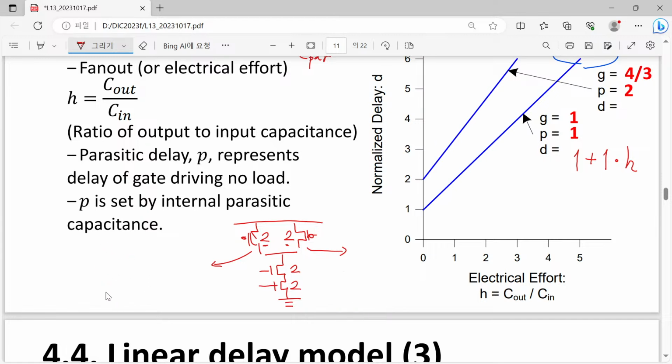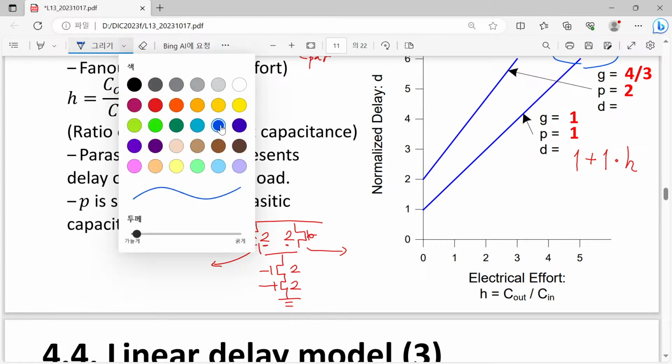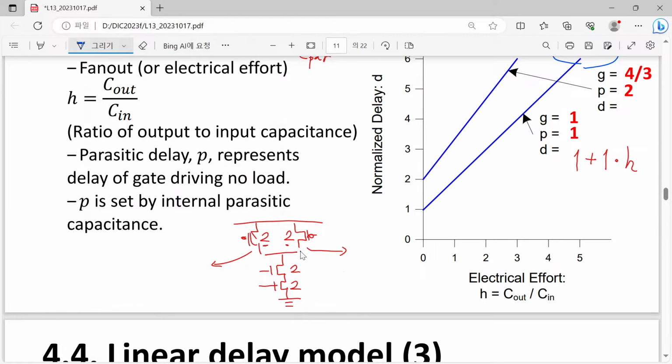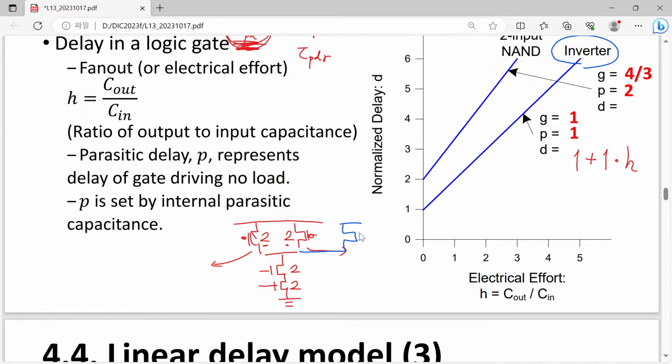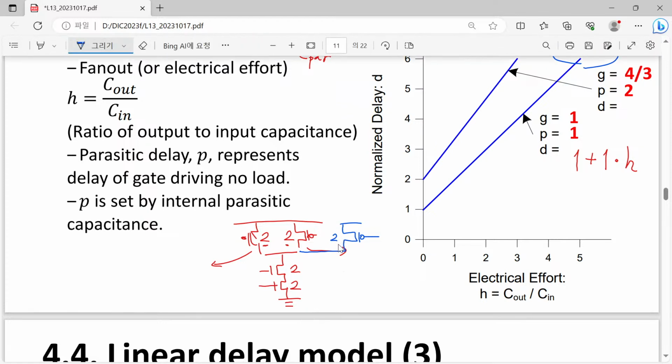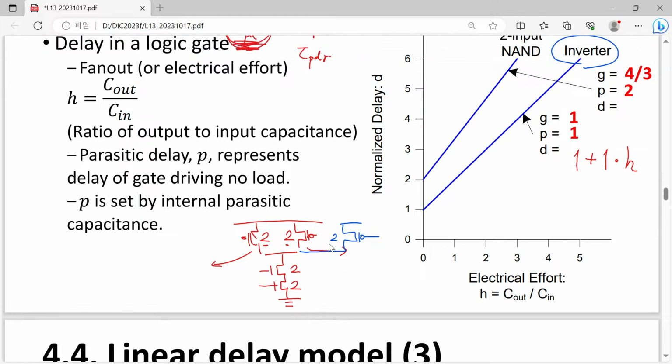So please remember our previous discussion on the 3 input case. How was our 3 input case? Even in that case, our PMOSFET had a width of 2, because our worst case was just one transistor being turned on. So yes, that was 2, 2, 2.